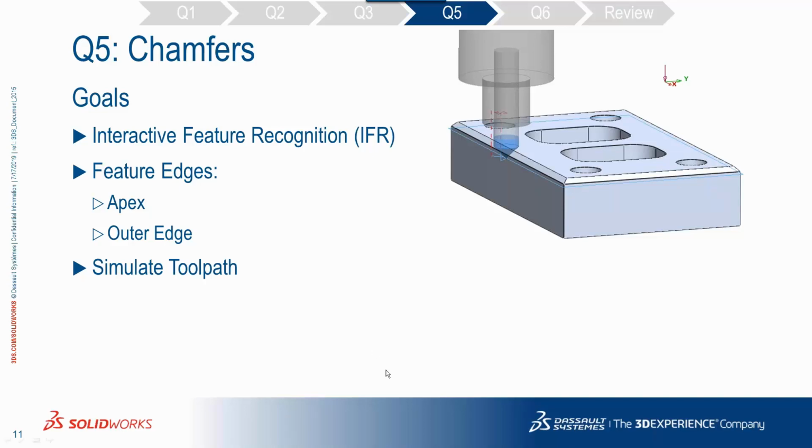If you have the physical chamfer, you can use the outer edge, or if you don't have it, you can use the apex. That's pretty much what we normally do if you don't have the feature by itself. Yeah. So what Santiago is saying, for outer edge, if the chamfers are modeled in your actual model, if they're designed in, then utilize the outer edge. Otherwise, if we look at the inside pockets, there's no chamfers modeled in.